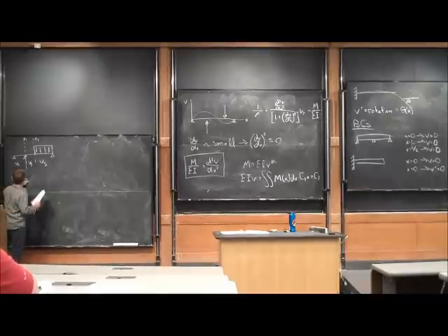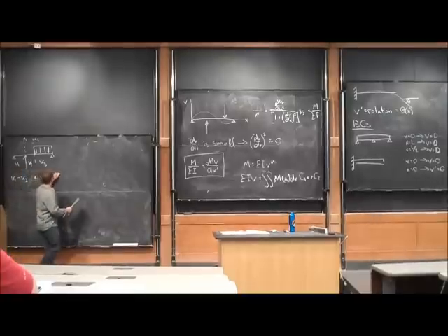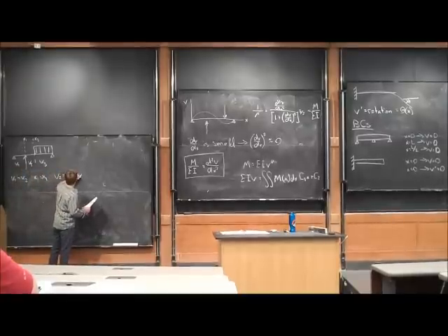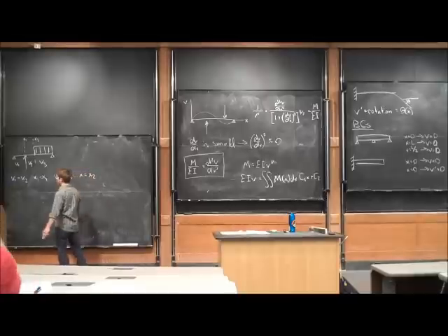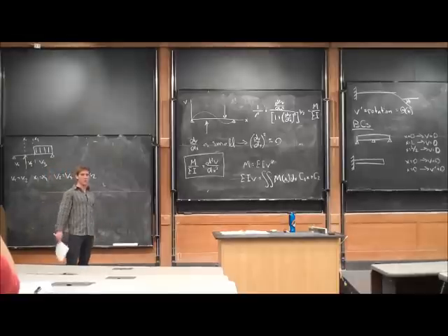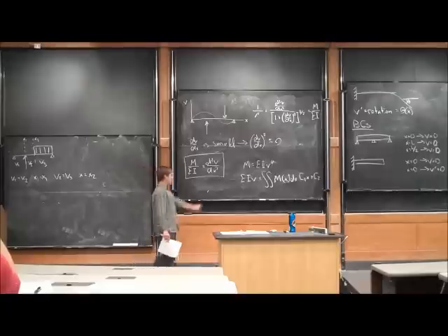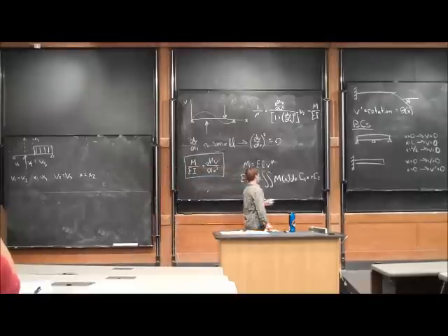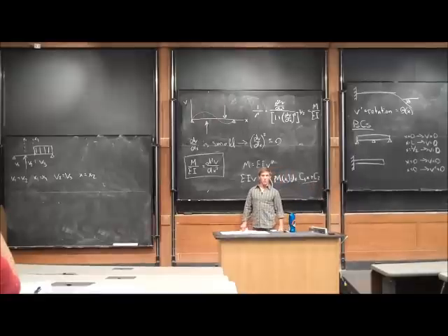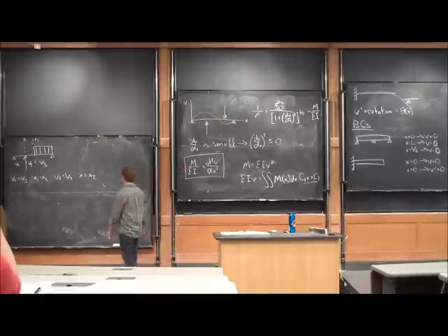V1 is going to be equal to V2 at x equal to x1. And V2 is going to be equal to V3 at x equal to x2, because you can't have any sharp breaks in deflection; it's a beam, it's a solid, it's all continuous material. Those are the main styles of boundary conditions you're going to have to use when you solve this equation. Every time you solve it, you will have two constants that you need to solve for. A lot of times they'll turn out to be 0 if you look at it in a clever way, but you're always going to have those two constants to solve for.